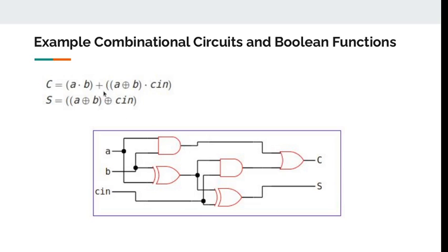And again, the operators inside here are the gates that we're going to build our system with. So actually, this is a full adder. This equation represents a full adder that we're going to use later in this course. We don't have to memorize this right now, but this is how you add 2 bits with the carry in, with the output of the sum of those 2 bits and the carry out, so you can move forward and have 8 bits, 12 bits, 16 bits additions of bigger numbers.